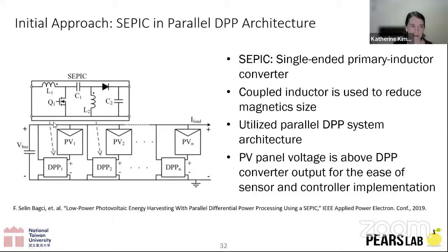Whereas if you have a parallel system like this, it depends also how it fails. Generally, with silicon cells, they tend to fail open, because I think a lot of the problems that happen over time are wire disconnects, especially if you had something that's moving. The wires will become disconnected, so they would be more likely to not short, but to be open. In a parallel system, if something becomes open, for example you lose a wire here, it just takes out that one, and the other ones are going to perform the exact same.